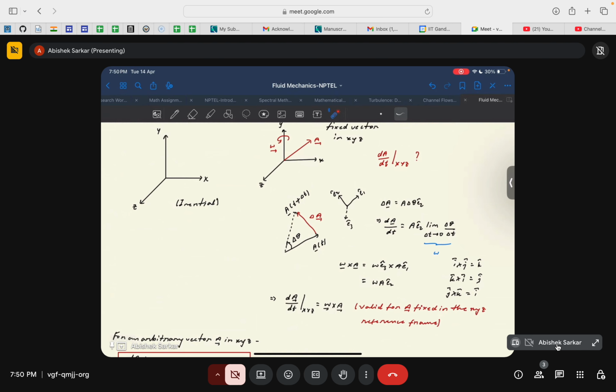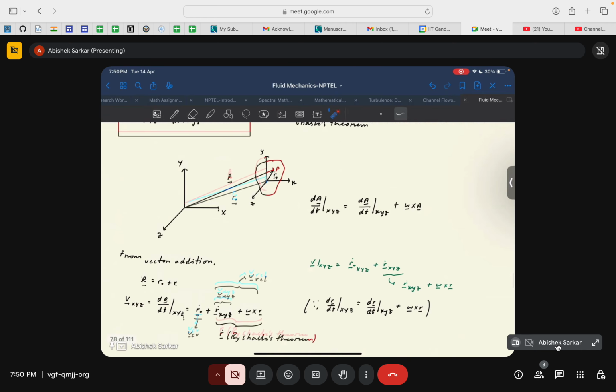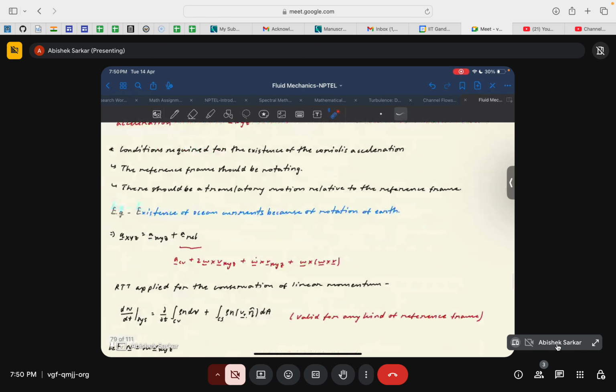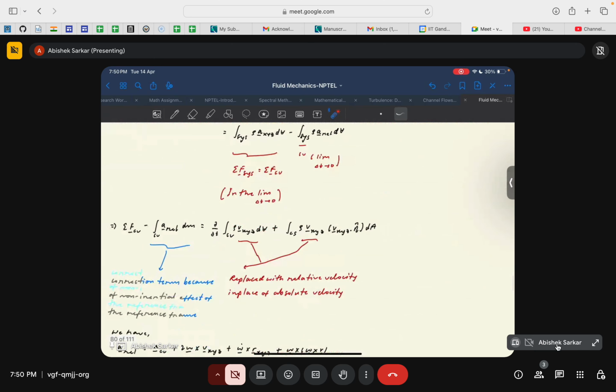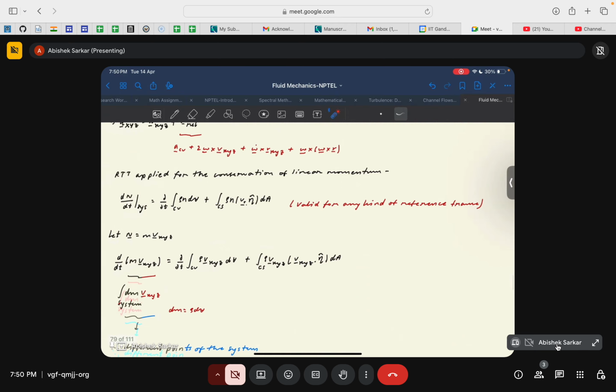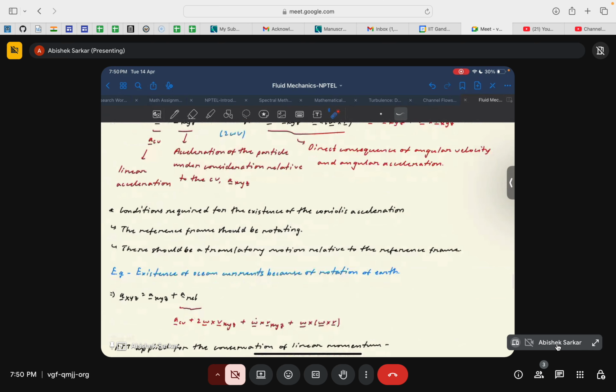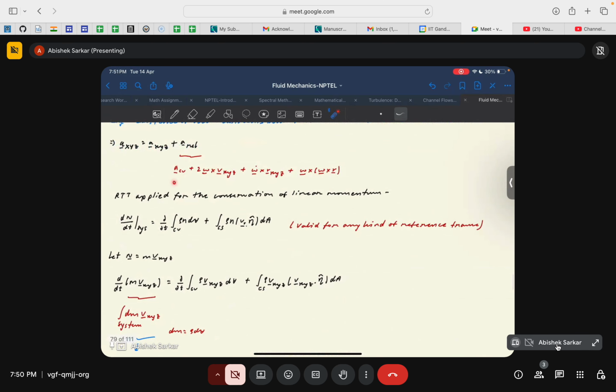Okay, but there are some instances or control volumes that are rotating, and any rotating frame inherently becomes non-inertial because of the rotational motion, which includes acceleration. So to take into account these rotating frames, we had to modify our governing equations, and we eventually saw that the final modification was that we end up with a velocity, force correction term given by this equation, where A relative is given by these terms. You have to see, depending on the problem, which terms will exist.